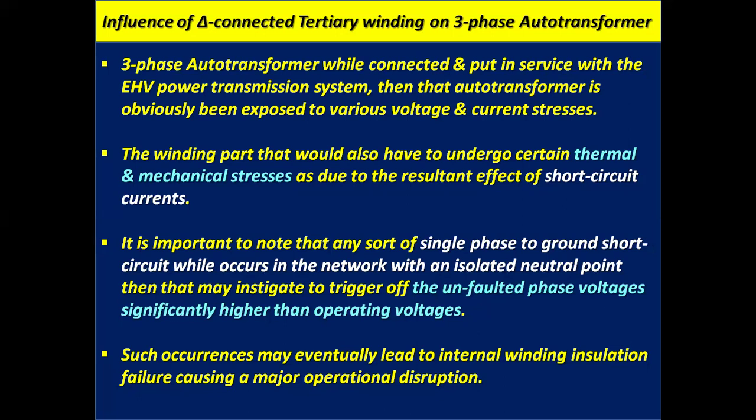It is important to note that any single phase to ground short circuit occurring in a network with an isolated neutral point may trigger the unfaulted phase voltages significantly higher than the operating voltages. Such occurrences may eventually lead to internal winding insulation failure, causing a major operational disruption.